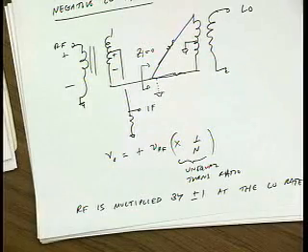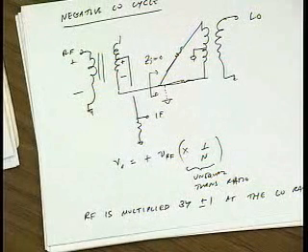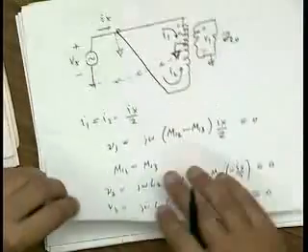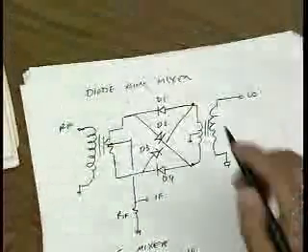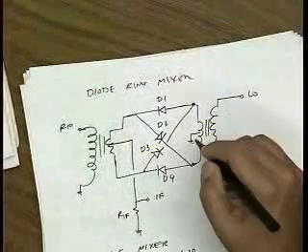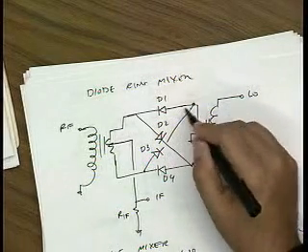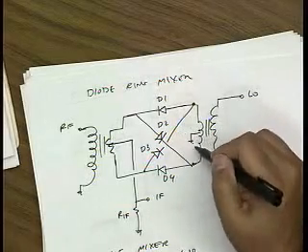Okay, any questions? So we can summarize the diode. Yes? Sorry, question. I'm not sure I understand why it's exactly symmetrical, because in one case you're looking into the P junction of the diode, in the other case you're looking to the N junction. The reason it's symmetric is that, from the LO's perspective, you're just turning on these diodes, right? So when I have a negative LO, I get a negative voltage here, which back biases D2 and D1, right? But it forward biases D3 and D4.